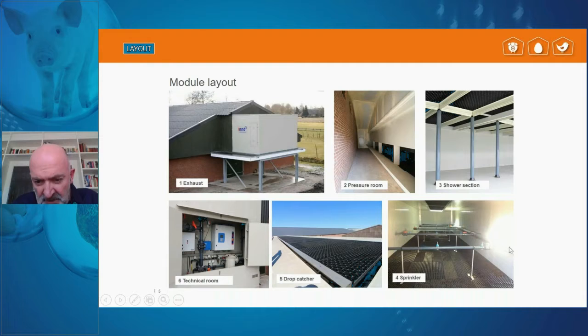And what we have here is a series of piping that is housing sprinklers, and the sprinklers spray the treated water across the packing material. That drops down into the shower section. The contact with the polluted air and the wash water happens during the packing material stage of the scrubbing process.